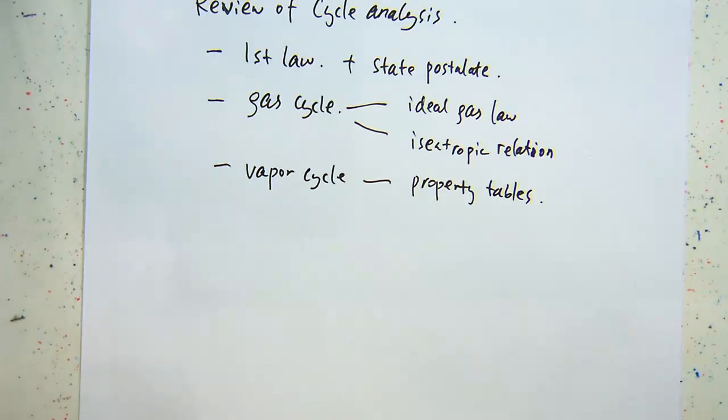If you're looking at the three cycles, basically we discussed three cycles, but for most practical cycles, that's more or less the same. The three cycles are the Brayton gas turbine cycle, including Brayton and the turbojet, which have almost the same T-S diagram, the refrigeration cycle, and the steam power cycle. For all of these three types, we're dealing with multiple states, multiple temperatures, but we're always dealing with only two pressures. In all three cycles, I should say the basic cycle, we're only dealing with two pressures.